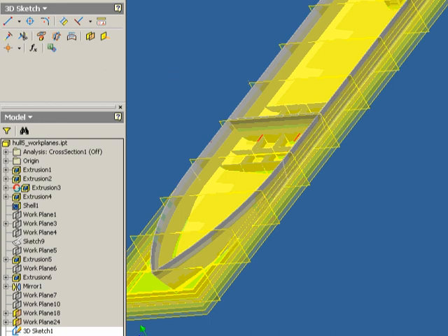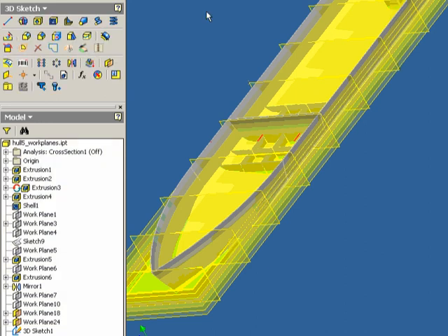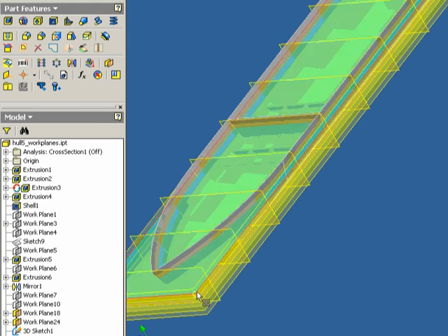We actually had to create what's called 3D sketches, and I'm going to create a 3D sketch. We actually had to draw or sketch lines where the waterline planes intersected with the hull of the boat. So that's really easy to do. You just simply hold the control key down and select a waterline plane. I'm going to select waterline 6, and you see how it passes through the hull of the boat. And also I'm going to click on the hull shape, the curved shape of the boat.